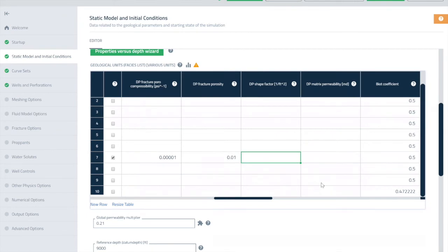I agree with the question exactly. But that's why what I would actually recommend is using a dual porosity model. In that situation, the fracture element pore volume is so small that you're going to have fluid flowing across multiple fracture elements, multiple dual porosity fracture elements. So it creates a broader region of pressure perturbation.